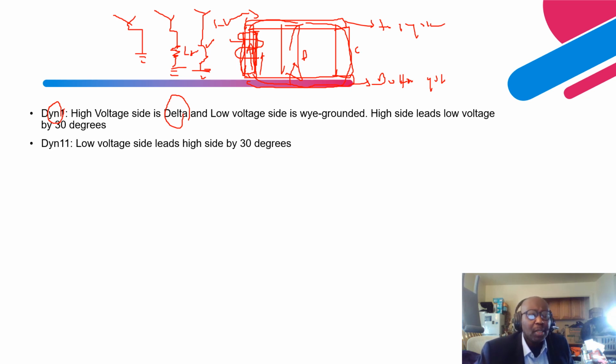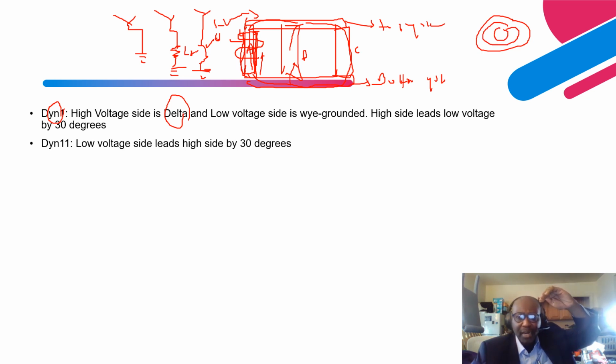Then, in between the low voltage and the high voltage, you have a cylindrical corrugated high density wood insulation. Remember, I told you that they are put like this. If you're looking on top from a pictorial view, this is how the insulation looks like, right? You have the core, and you have the low voltage, then you have these cylinders.